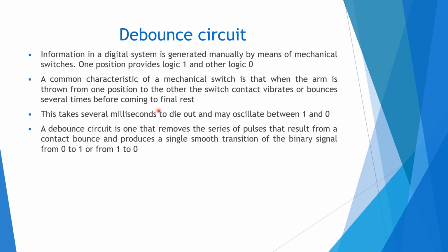So the next topic is the Debounce circuit. Usually to enter information into a data system, we use a keyboard or such keys or a mechanical switch, where one position provides logic 1 and the other logic 0. But the common characteristic of a mechanical switch is that when we press it, the switch contact vibrates or bounces several times before coming to the final result.